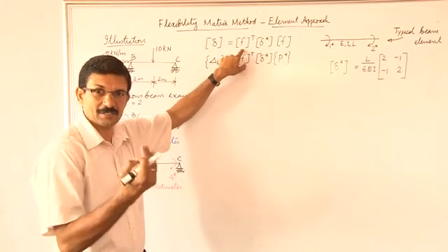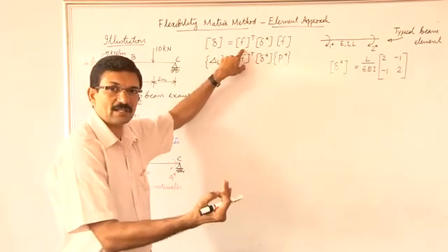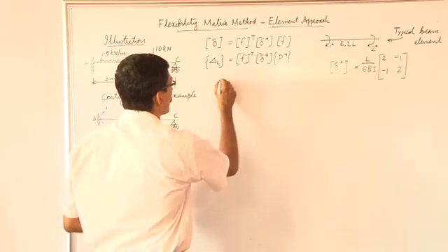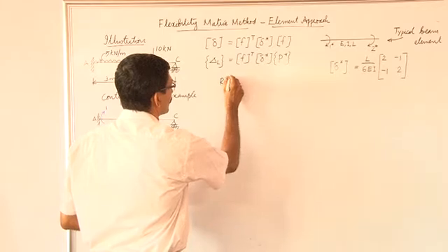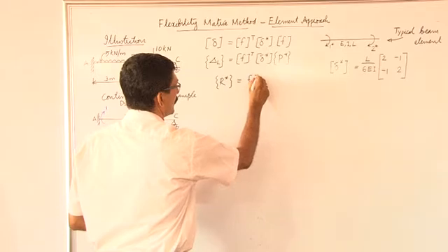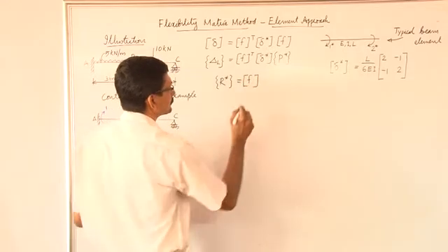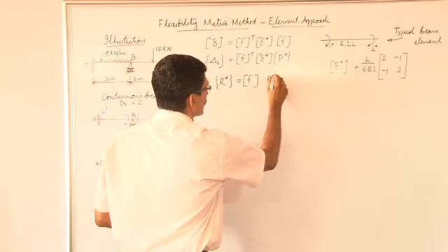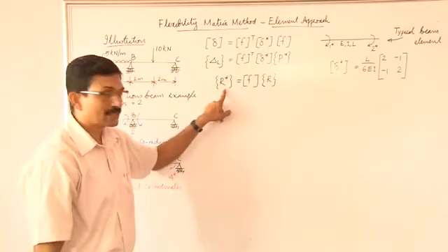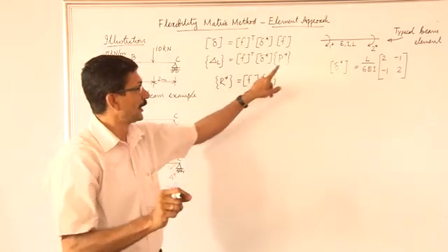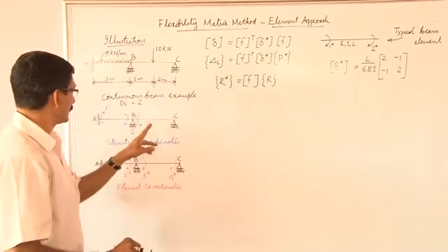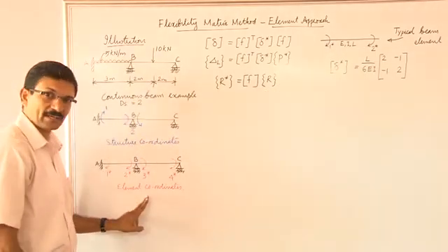That is essentially a connection between the element forces and the structure forces, defined as R star, which represents a vector of element forces, is equal to the force transformation matrix into the structure forces R. More precisely, this R star contains forces corresponding to element coordinates like 1 star, 2 star in this typical element, or in this example I have given the element coordinates over here.